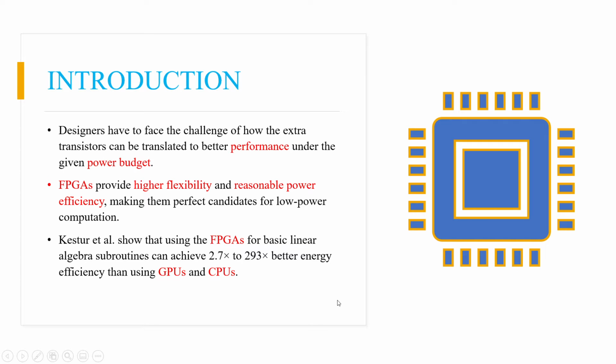The architecture is easy to use and meant for general purpose computation. It consists of a CPU layer, an FPGA layer, and a DRAM layer. It takes advantage of through-silicon via (TSV) based 3D IC technology to provide vast FPGA resources close to the CPUs.